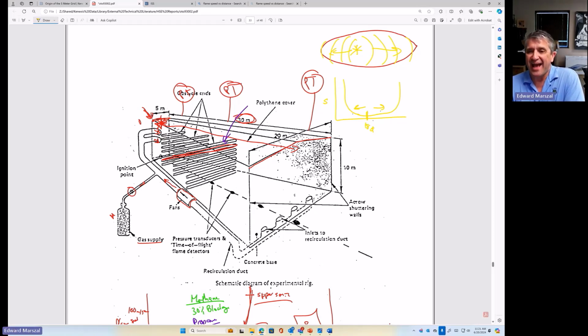So if you ignite a gas cloud in the middle, the flame speed is going to get cut, and the amount of overpressure is going to get cut. It's as if you would just ignore half of the gas cloud, and you're only getting your explosive overpressure from that side, or just from this side.